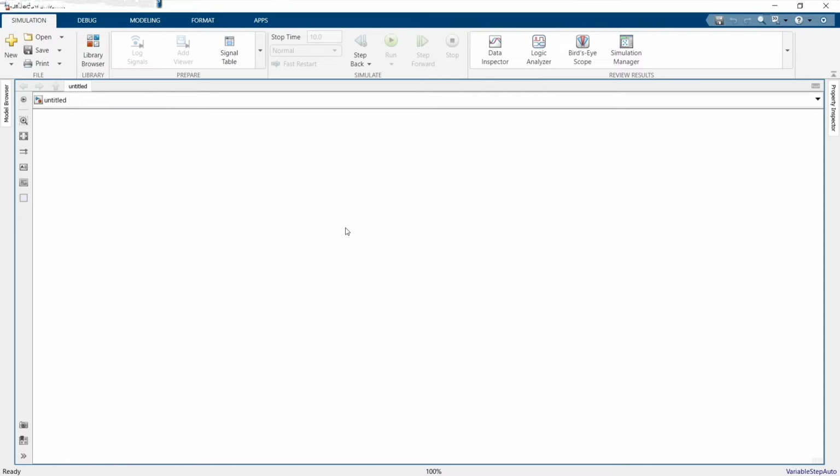Now in here I will also use an IGBT in order to create a source cutoff. So I will use a source cutoff IGBT in order to control my DC voltage cutoff from my boost power converter. So for that I will call another IGBT and let me connect that in here. For that I have to delete this connection and again I have to connect the IGBT. Now my boost converter is completed.